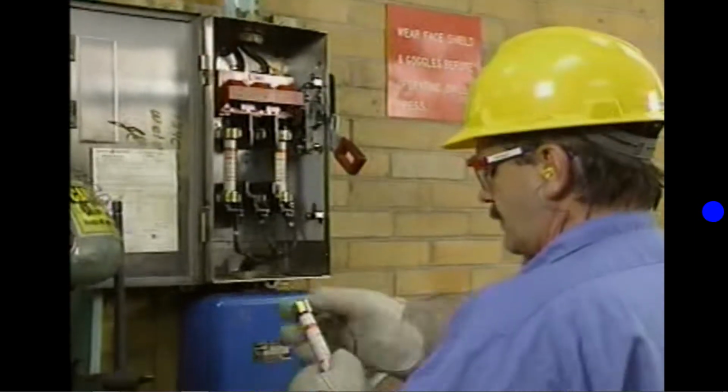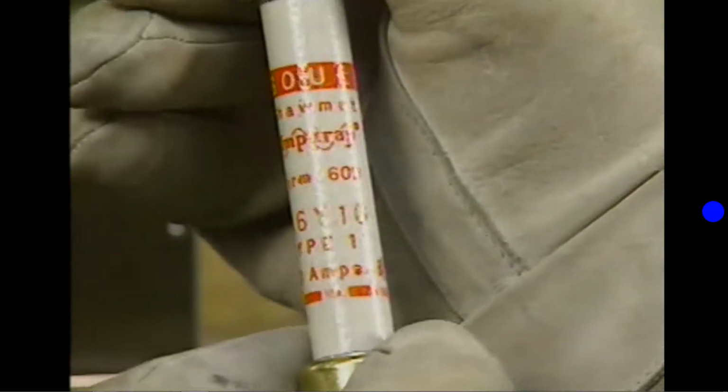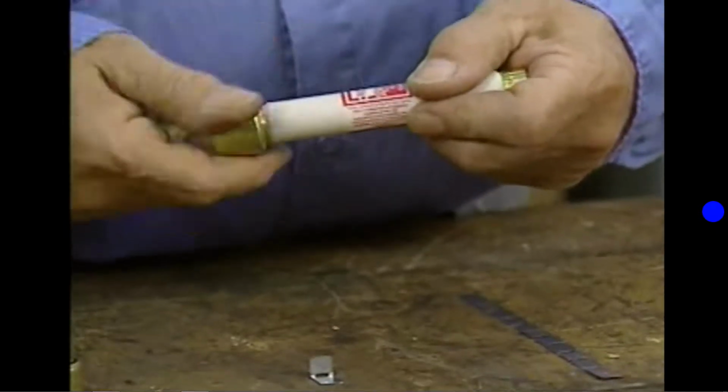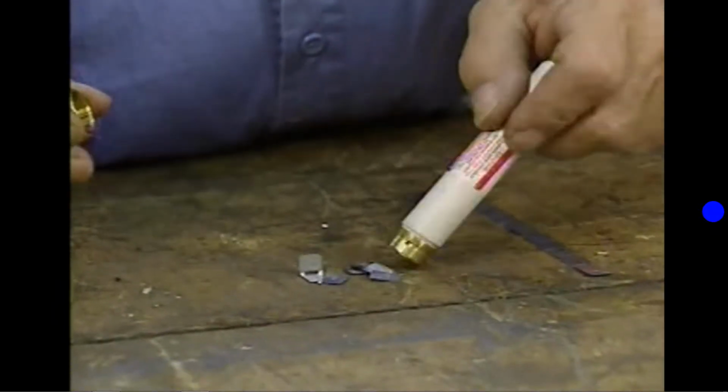A fuse is a device containing an element that melts when current flow through it rises above a designated value. When the element melts, the path for current flow through the fuse and therefore through the circuit is interrupted. This condition is commonly referred to as a blown fuse. Many fuses cannot be reused after they have interrupted current flow and must be replaced. There are also fuses in which the element that melts is part of an internal component that can be replaced.